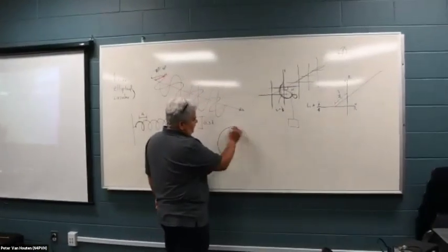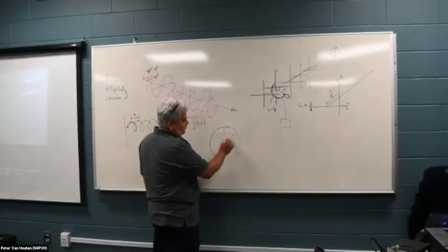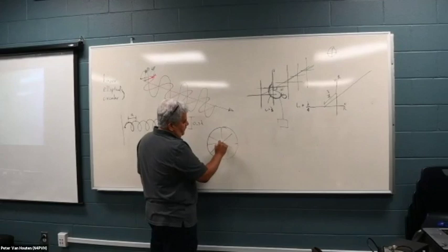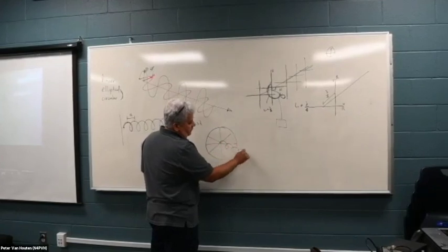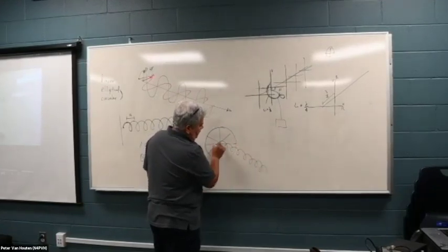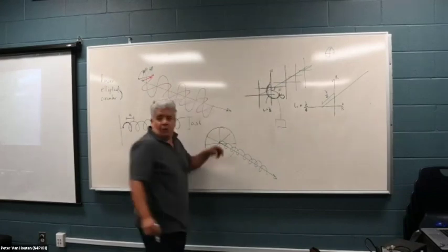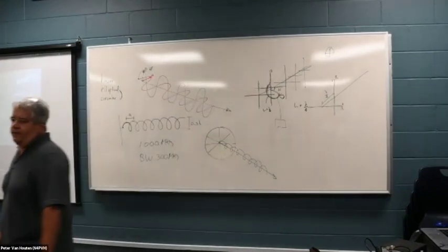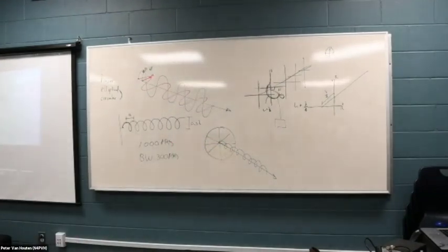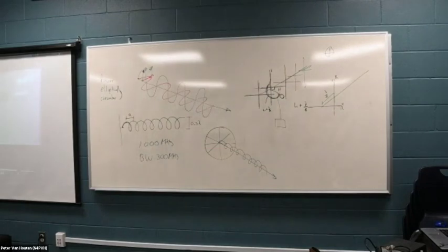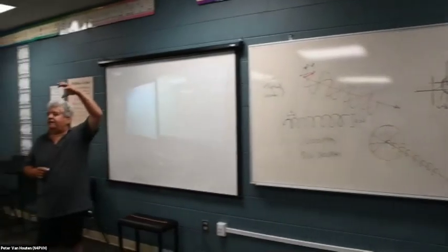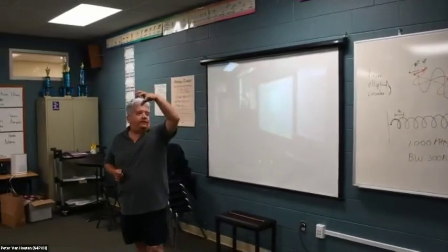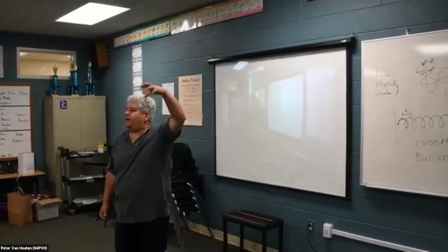Normally you have a reflector, with some spokes here to hold it, and then you get the helix, and this is the axial mode. That's the direction of transmission. One thing is that these antennas can be put at the focus or the center of radiation of a parabolic dish.